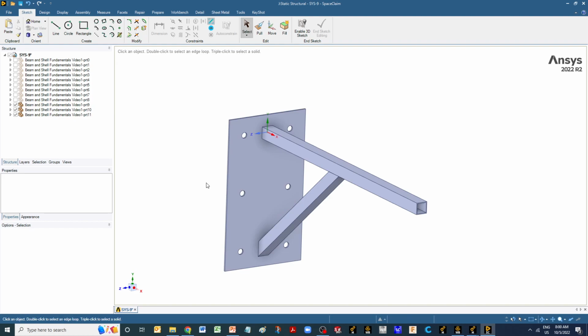Before we get into finite element analysis, it's important that we have some sort of an idea of what the structure can bear. What is the magnitude of load it can take, and a lot of this can be done using simple formulas from solid mechanics, like the bending and flexure formula, the torsion formula. We can even evaluate buckling loads, and using that we can come up with a rough size or geometry of the structure, and then we can dive into finite element analysis. We can also use hand calculations to basically validate our finite element analysis.